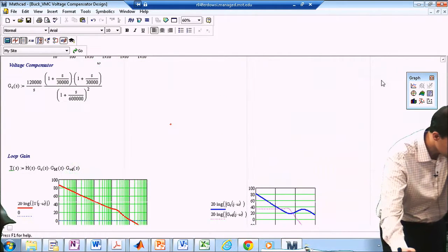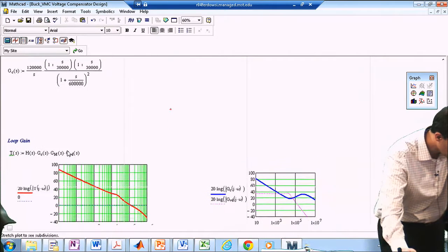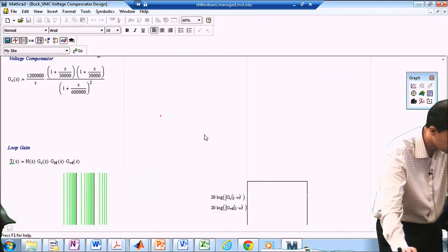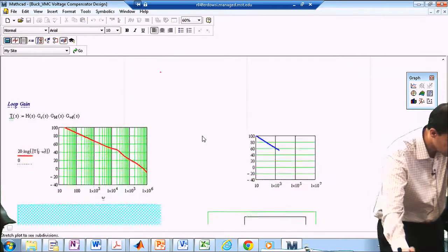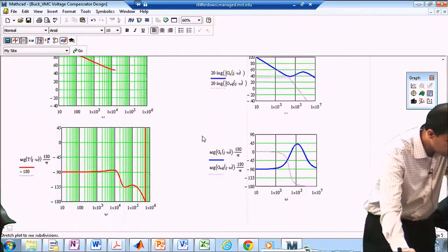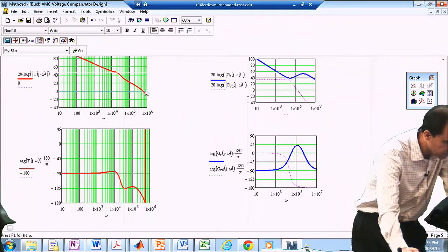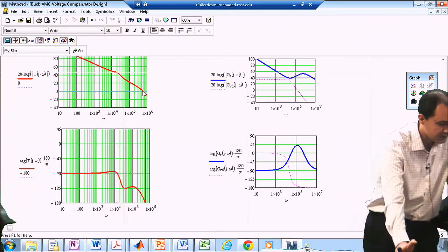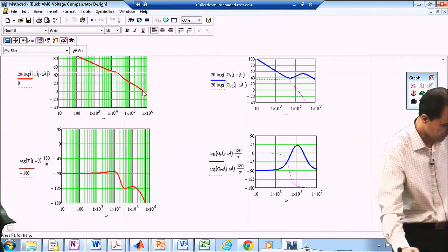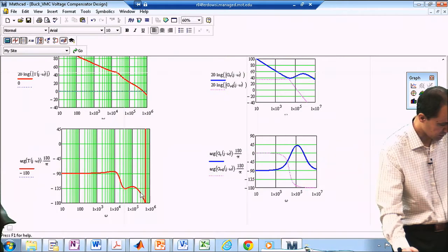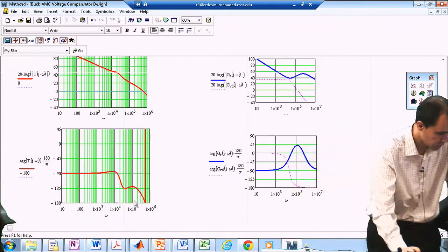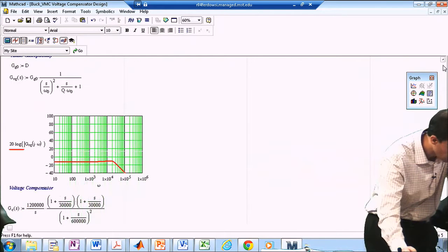the switching frequency. It's really hard to make this system unstable because a buck converter is inherently stable, but let's go to this even 10 times larger number. And so I keep increasing my gain. Now I have a very high bandwidth, but my gain at the switching frequency is about the same, which is 1, which is scary. And the system is still stable. I'm just having a lot of ripple in my output because I'm not doing a lot of attenuation. I'm going to show you the time domain simulation as well.